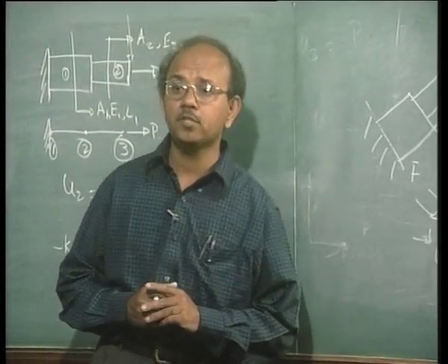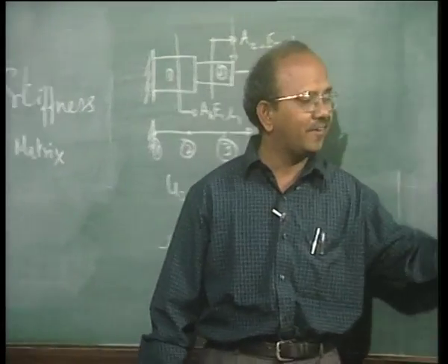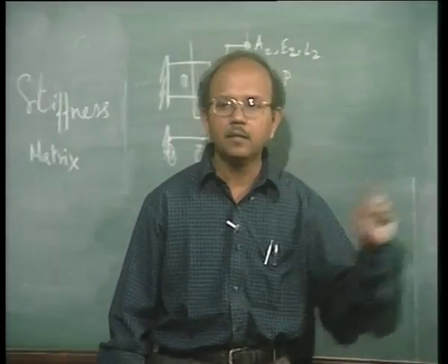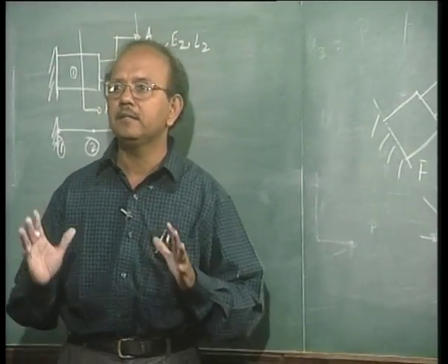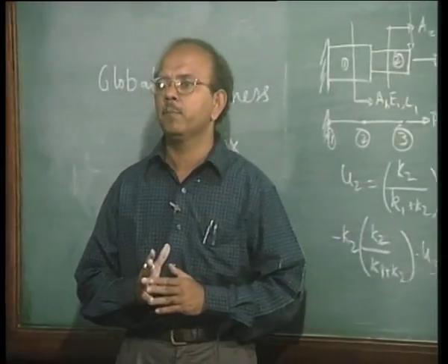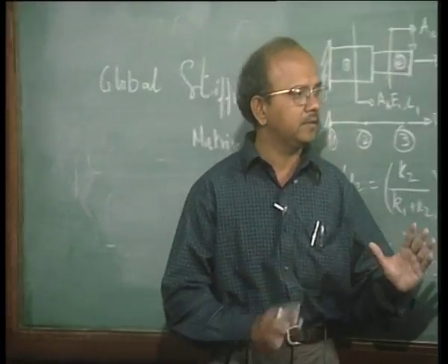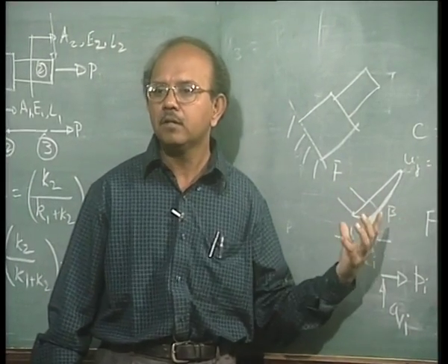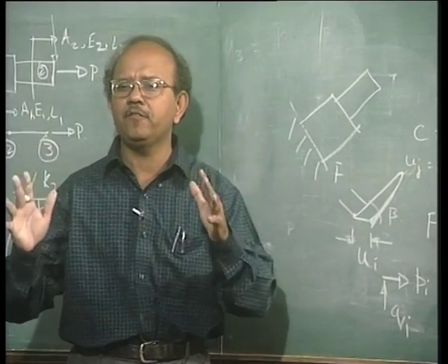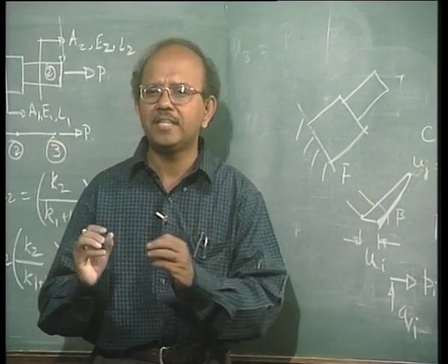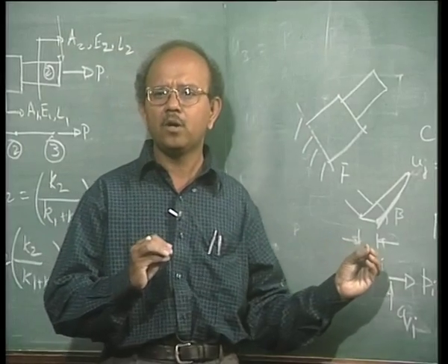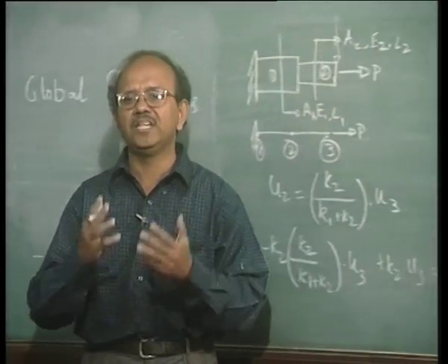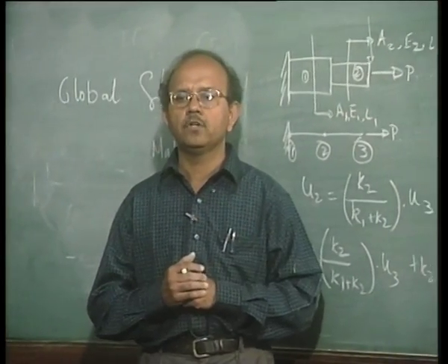In other words, it is possible to develop the stiffness matrix of an inclined bar by following the same steps, but by resolving the forces as well as displacement along the axis of the bar. So my physical behavior of the bar does not change, but I change a little the mathematics that is involved, so that I am able to define a more general inclined bar.